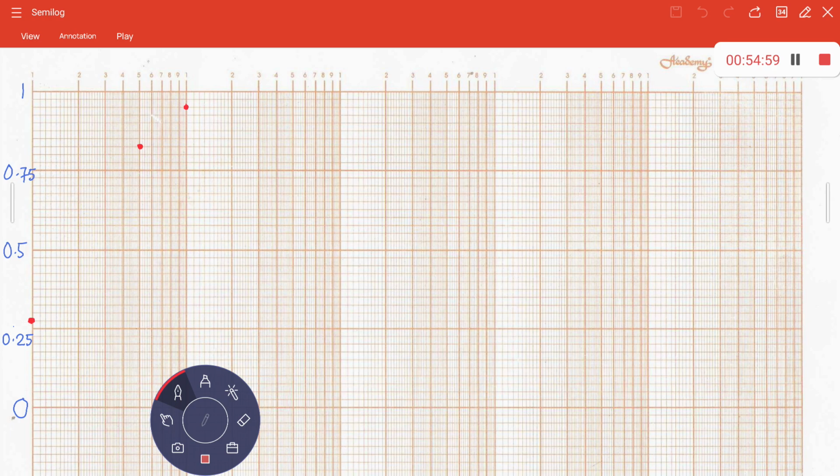I've got 3 points: 10 Hz, 50 Hz, 100 Hz. You can take more points as well. You can take 20, 40, 60, it doesn't matter. But at least 3 points, so that you can find out what should be the corresponding variation of the graph. Okay, 100 Hz, 0.94. Then you go to the 1K part only, because already it's towards saturation, right?